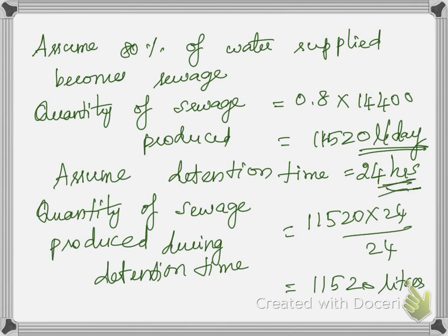Another will be that the quantity of sewage produced is in liters per day. So one day will be equal to 24 hours. That's why we are putting one more 24. And the quantity of sewage produced during detention time will be 11,520 liters.